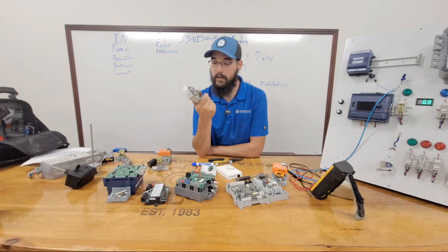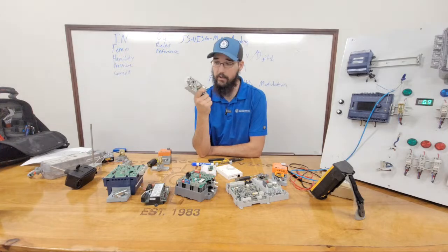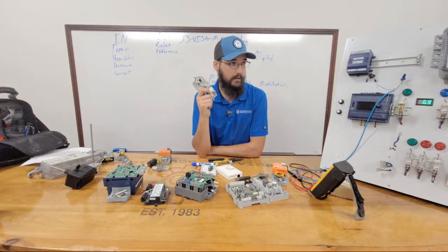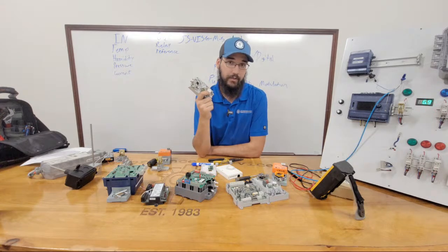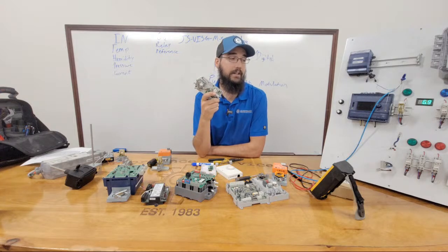And a lot of times what can happen is the gears in these are plastic. They inevitably break. They hit a weak point. And you'll start to hear this thing click, click, click, click. That is an indicator that you have bad gears and they need to be changed. Now, when those gears are on the edge of failing, or you have an actuator that is constantly having calibration issues, it's usually because you've got a gear issue.